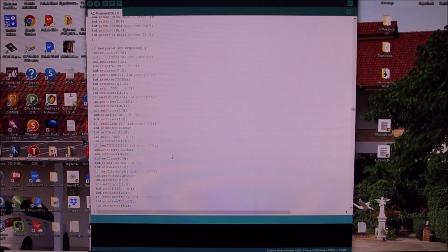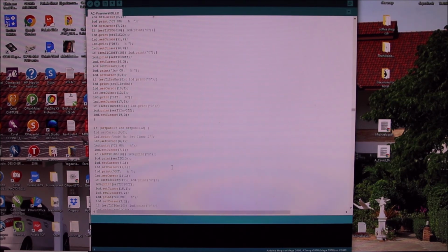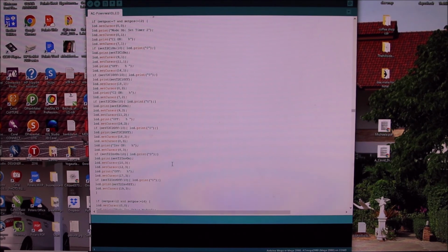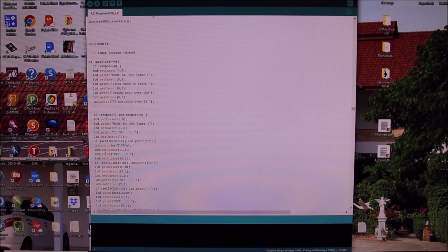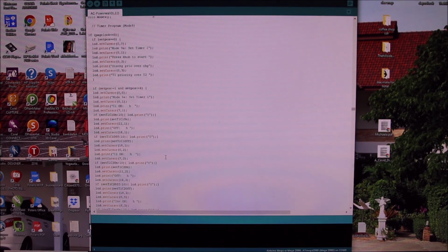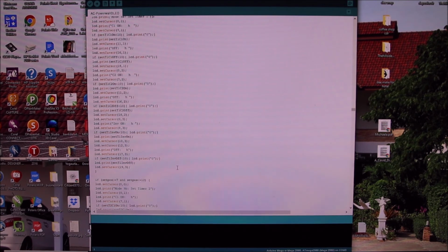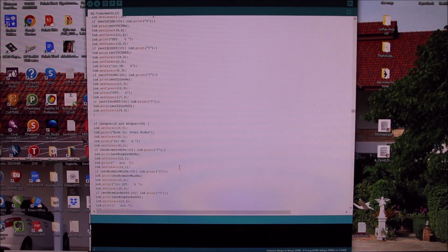And that is not allowed to do, because that takes too much time to build up the screen information, and that would slow down the rotary encoder so terribly that it basically would not work. It would just bounce around. So when I enter the setup mode, I build up the screen once, and as long as there's no change on the screen, there's also no new build up.